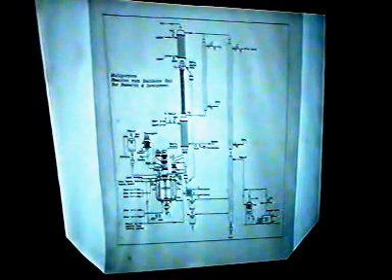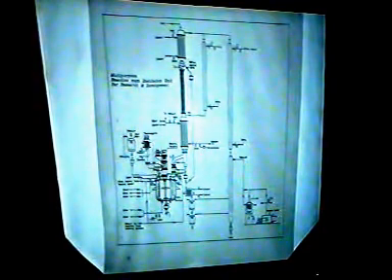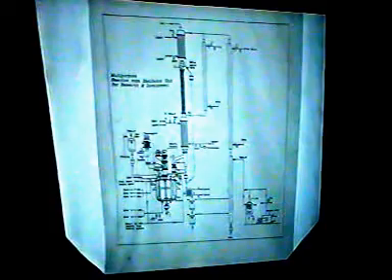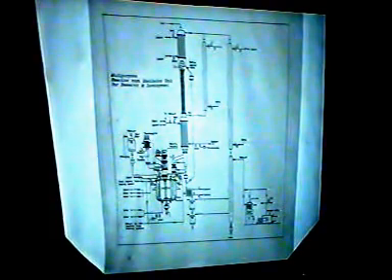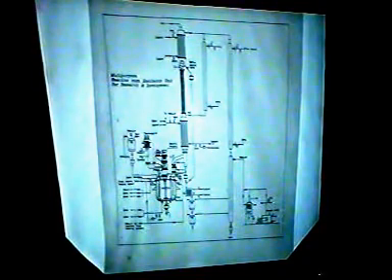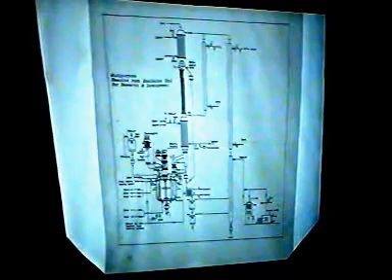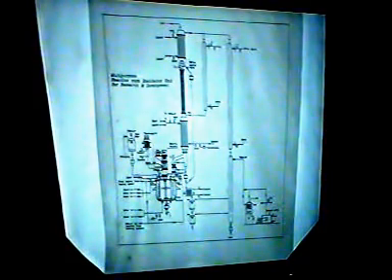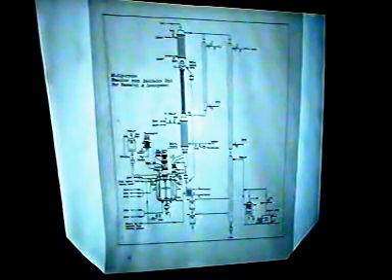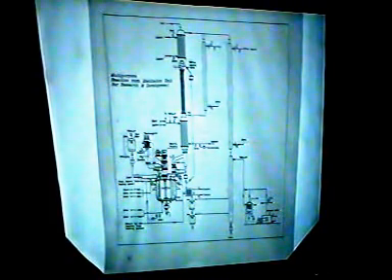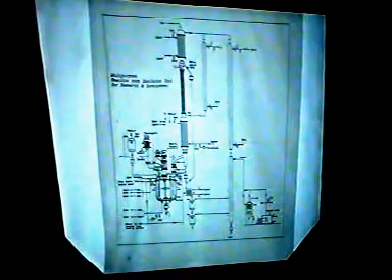Now, many times we need to change the pattern of the stirring. Sometimes we have to have an anchor to negotiate with some solids, and sometimes we have to have a turbine stirrer to stir properly the binary systems. So we need to change them very often, and therefore we are giving a system wherein this vessel can be lowered down by means of a jack or by means of a trolley, and the same can be attached again after replacing the stirrer.